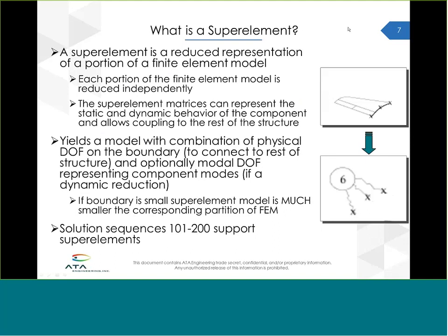So the first thing we need to address, of course, is to say, what is a superelement? Conceptually, it's really just a reduced representation of a finite element model. You start out with a detailed model, you make a reduced representation of that, which has many, many fewer degrees of freedom, but still preserves the accurate stiffness, mass, damping, and optionally dynamic characteristics of that detailed FEM.